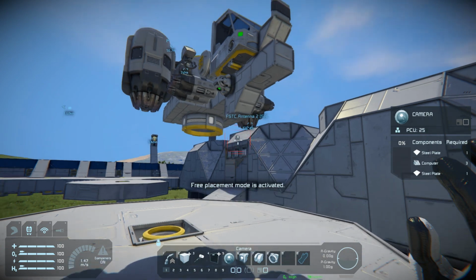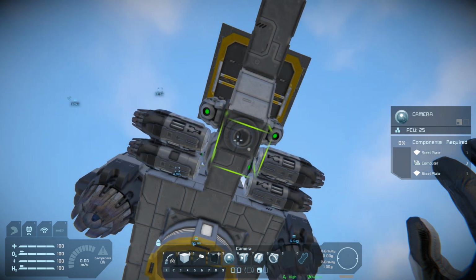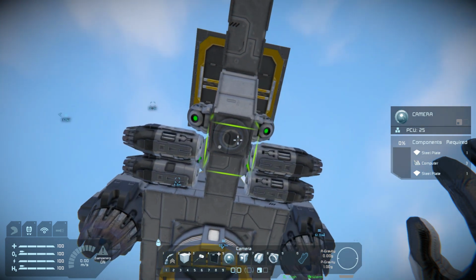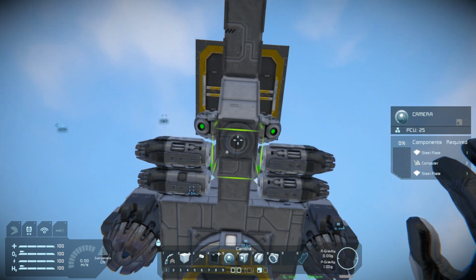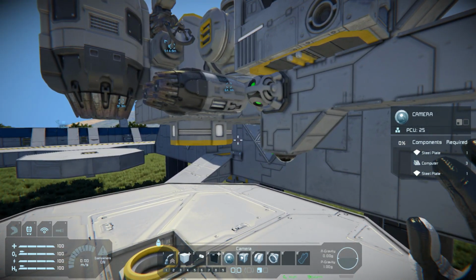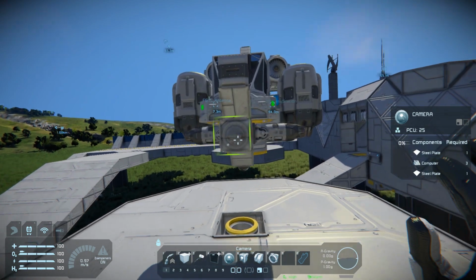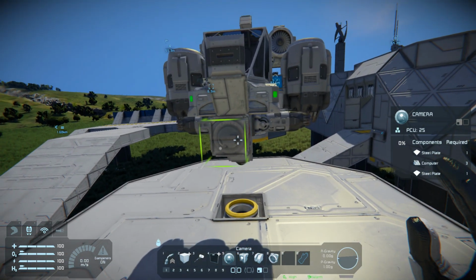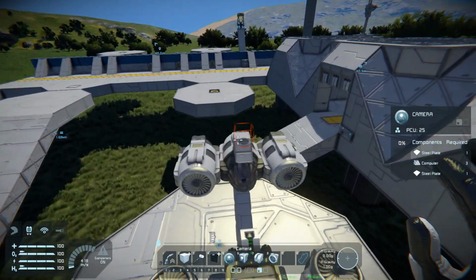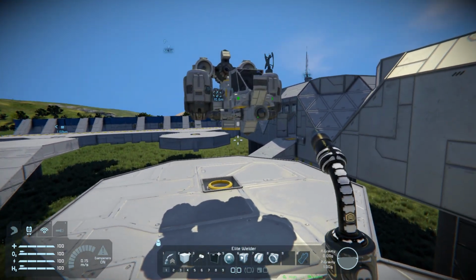Cameras are really important because SAM uses cameras to measure distances. I think the whole thing is done with raycasting, but I'm not perfect at this. Cameras need to be positioned at the outermost edges, kind of, on your ship. You want basically the cameras to be the last block that sticks out from everything. We need one on the bottom, so it can measure the distance from the surface. We need one on the front and one on the top, and we later need to name them correctly.